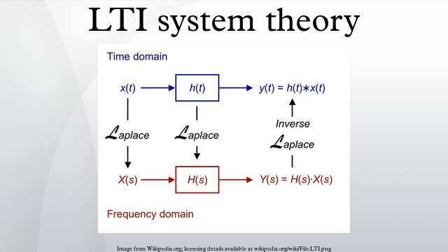To understand why the convolution produces the output of an LTI system, let the notation represent the function with variable t and constant a, and let a shorter notation represent it. Then a continuous time system transforms an input function into an output function, and in general, every value of the output can depend on every value of the input. This concept is represented by the transformation operator. For a typical system, the operator depends most heavily on the values of the input that occurred near time t. Unless the transform itself changes with t, the output function is just constant, and the system is uninteresting.